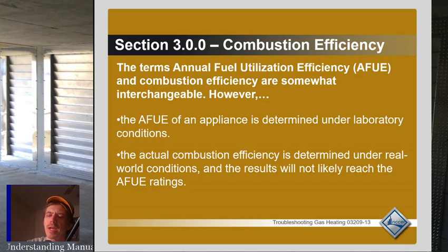You're supposed to clock your gas meter and determine how many BTUs you're actually putting out. That way you can actually determine what's going on. And use a combustion analyzer to determine the actual efficiency. But your numbers do end up so close enough that the margin of error is still there. So I guess the greater point is that you'll never really reach that AFUE, and you'll very rarely put out the exact BTUs that a piece of equipment says it will. But it's so close, you're within the standard margin of error of what we do, so it's really not that important to get those exact numbers.